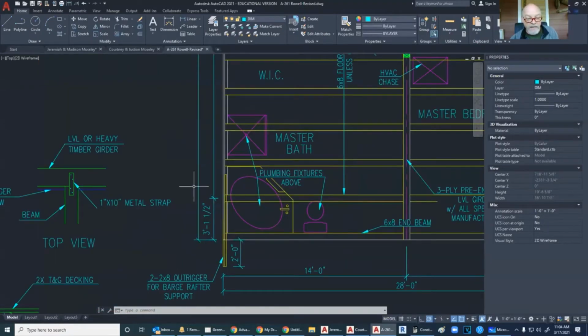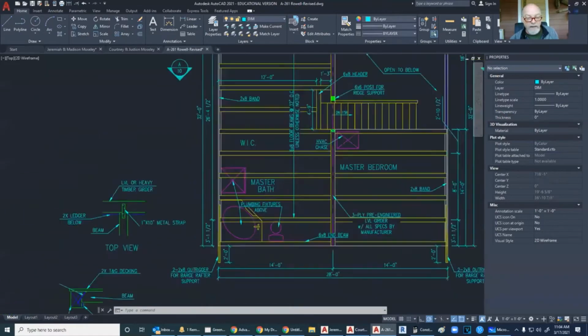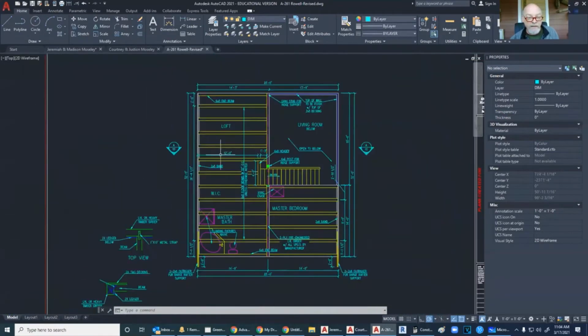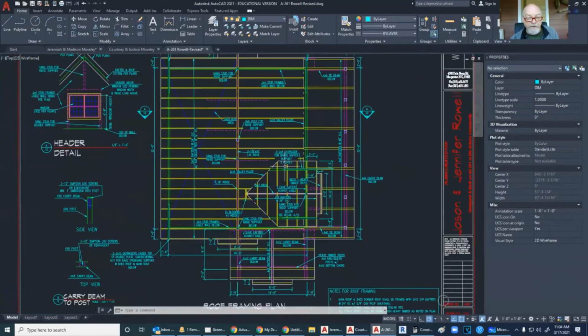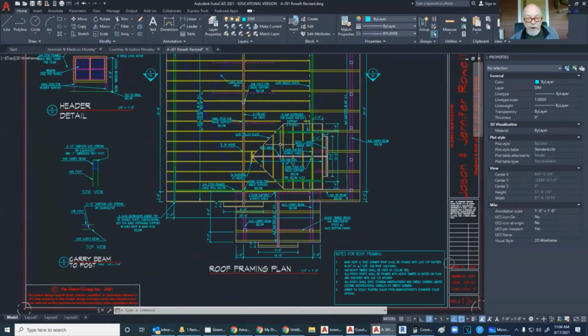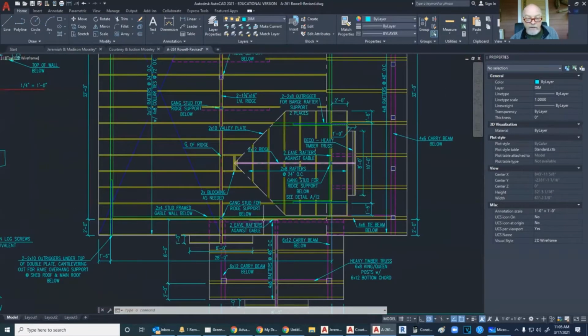Obviously, you see that on one side we have 3 1/2 space over here, where over here we have 2x6, and then these are 32 inches on center. We go to the roof, the same deal. We do this so that they know where all of these things are going to run and hit and fall.